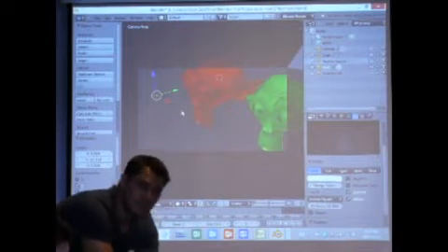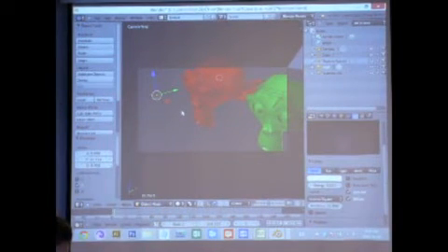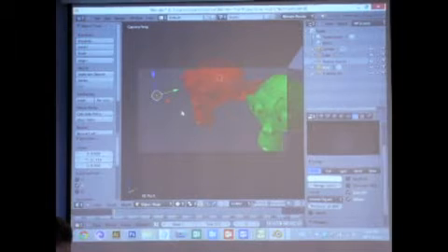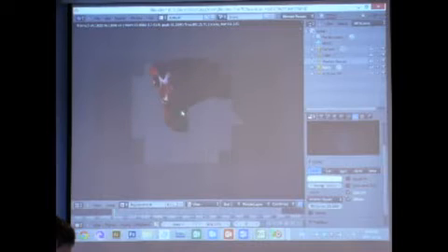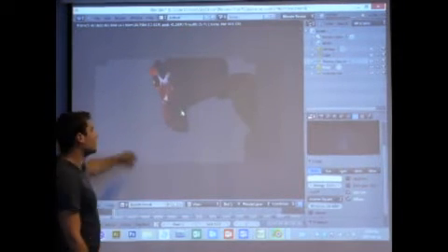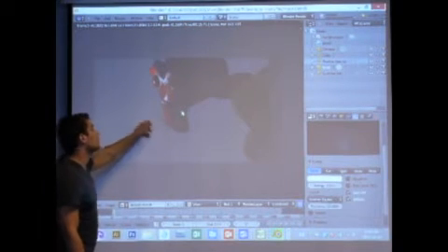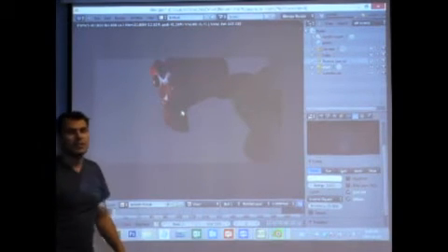And of course, you can duplicate these lamps the same way with Shift D. You can make a whole bunch of different lamps everywhere and increase the brightness, so they make much more light. It's always good to see how it looks by pressing F12. Because I put a light source here, it will never show up in your actual render, but you will see the effect that it has.